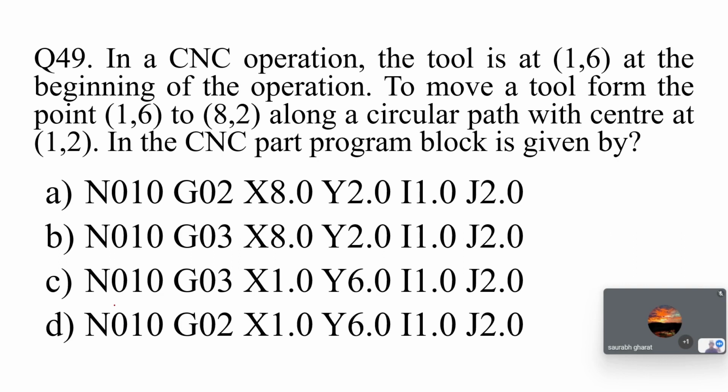After 2 to 5 minutes, I will solve this question, but try it on your own. It is very important and it's from your assignment only, so try it by yourself. After that, I will go through the solution. The important part here is the G02, your start point, end point, and your center. Consider this point while marking the correct answer.